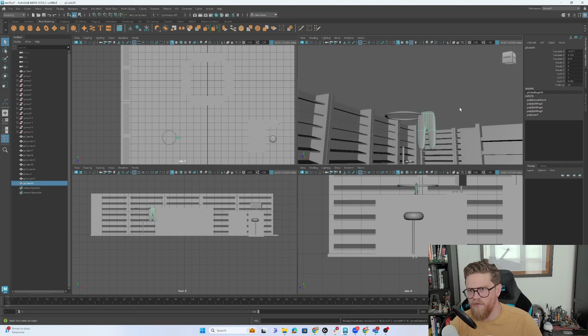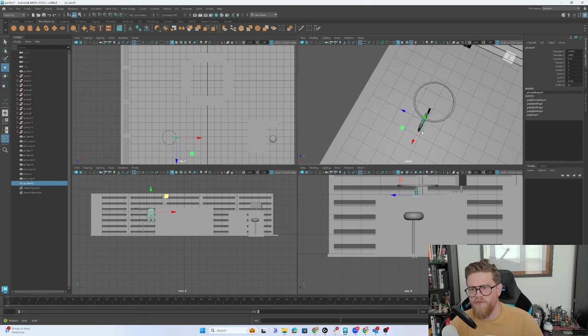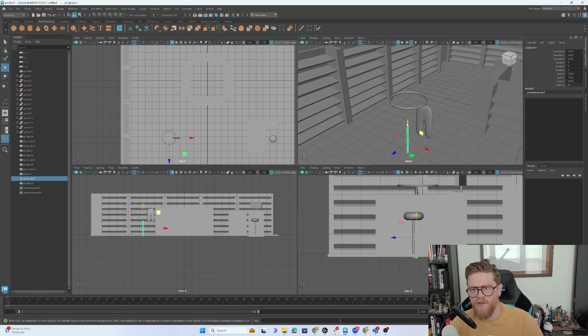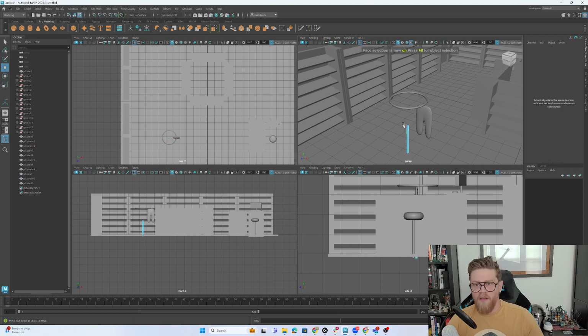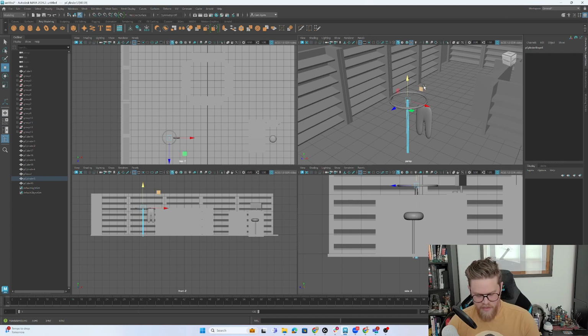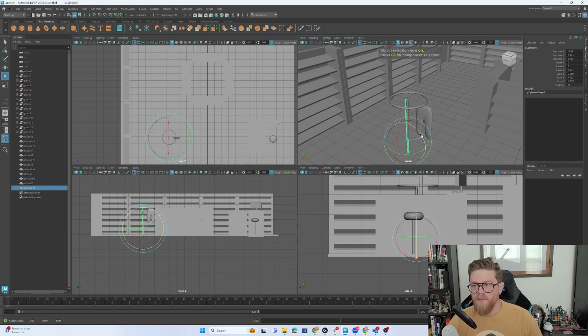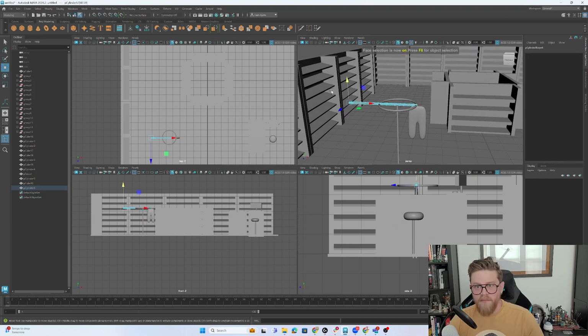So again, to get it to preview smooth, I've just hit 3. Nothing more fancy than that. And I'm just going to say that it has some type of strange connection to this thing that I don't need to really care about. F11, grab the top, unselect, pull it up so that it's about the same height. F8, duplicate, rotate to 90, just so that we have points that it is touching the top circle here, so we're not floating in midair. Pull it all back down, over just a little bit.